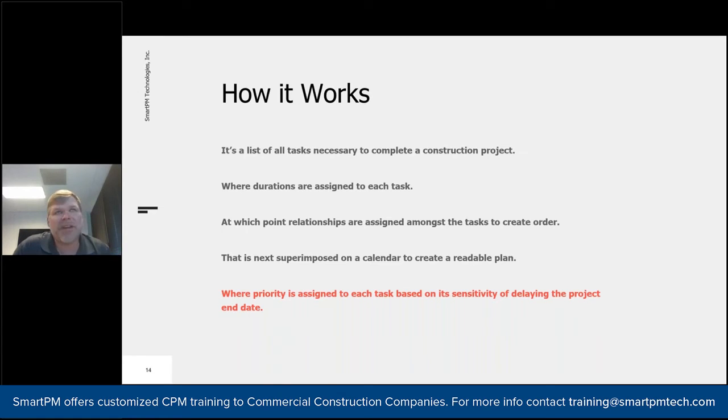For instance, you can't put on level 2 concrete without level 1, or you can't put a roof on a building without a structure. You know, there's things that you just cannot do. And then there's preferences of what order of operations do we want to follow amongst the trades going through a specific area, or what sort of crews do we want to move from area to area to area for each specific trade. Those are things that you need to lay out in the schedule, using the predecessors and successors, saying a predecessor being something that happens before, a successor being something that can happen after.